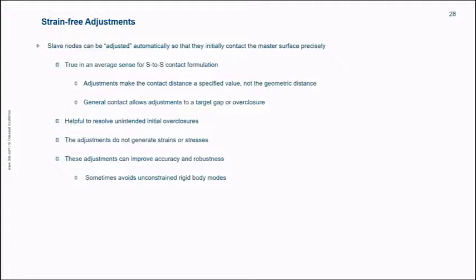Sometimes if you're doing contact pairs or general contact and you have commands in there to generate a press fit, then the COPEN might not be what you think it is. So it's best to do data checks without any commands that treat the interference as a press fit, and then look at your COPEN values and then decide what to do from there. Okay.